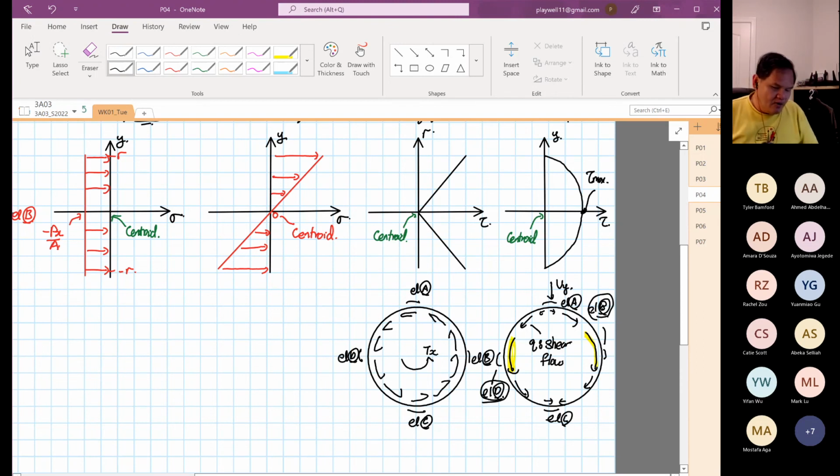Later on, as I say, this is known as your shear flow. Now, if we were to combine the torsion and the normal stress, I want you to focus on these elements down here. The yellow one is due to the torque. The blue one is due to the shear force. Now, which element will see the higher shear stress, element B or element D? Anyone? It's 50-50, you can make a guess, but you have to explain to me why. Tyler? That would be D.